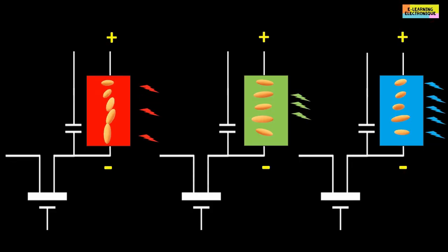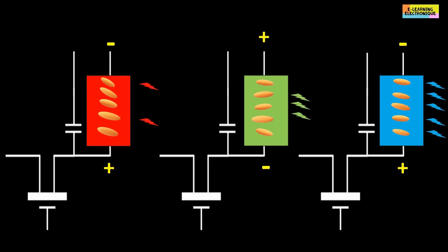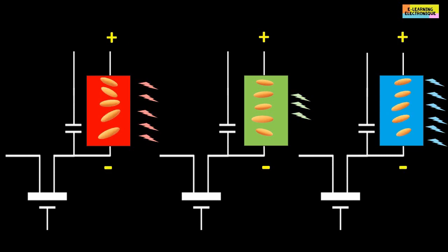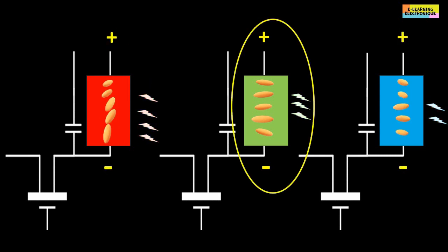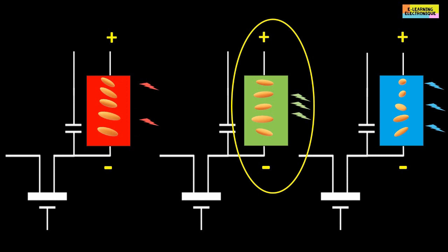Another element to take into account to preserve this electrical property is to avoid applying a voltage with the same polarity to the liquid crystal over a long period. Doing so may freeze the liquid crystal and make it unable to change its orientation regardless of the electric field applied to it.